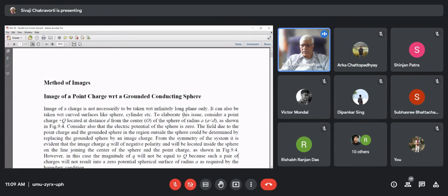Well, nowadays you have very good switches. 3 to 30 volt are very low voltage switches, which are typically used in electronic circuits. But in power circuits, we can even go up to 3 kV. It is possible. They are available. But still 3 kV is not 33 kV. So then we have a problem in our lab. So in those cases, please remember this, sphere gap is the perfect switch.